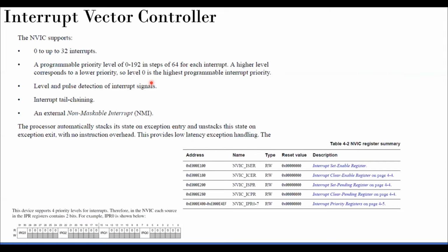And situations can come where two interrupts have the same priority level. Then of course, first come first serve is the only solution. And the important part actually is just to confuse you. Sorry for that. This is the information provided by Cortex M0 Plus, but our Freedom board has a slightly different approach, which is actually shown here. So this is what the Freedom board follows.